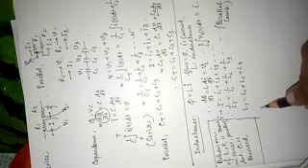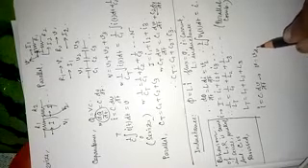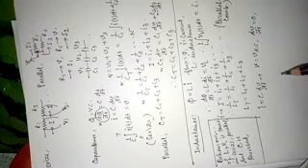One thing is very interesting, everyone should know this. We know that for capacitance, I equals to C dV/dt. Now if V equals to a constant, then dV/dt equals to 0, so I equals to 0.